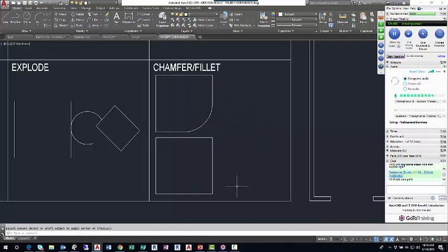So you're going to use fillet to sort of soften edges, you're going to round corners. It's not a continuous command like offset and line. If I want to offset more, I'll go offset, left click, you know, I can restart the command. Or I can click fillet, left click, but I'll click multiple this time. Now I can left click this corner, left click that corner with fillet, and the command's still going because I said I wanted multiple. And there we have it. I've filleted all 4 sides of that.